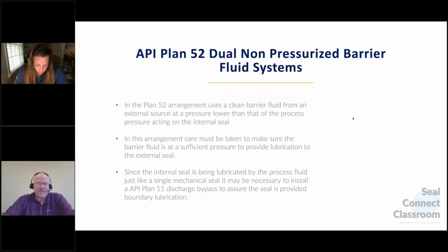If you don't, one thing you can do is take combinations of single seal environmental controls and add them with double seal environmental controls. You may run discharge bypasses where you can elevate the stuffing box pressure for the inboard seal in applications like this, where you get good lubrication of the inboard seal.